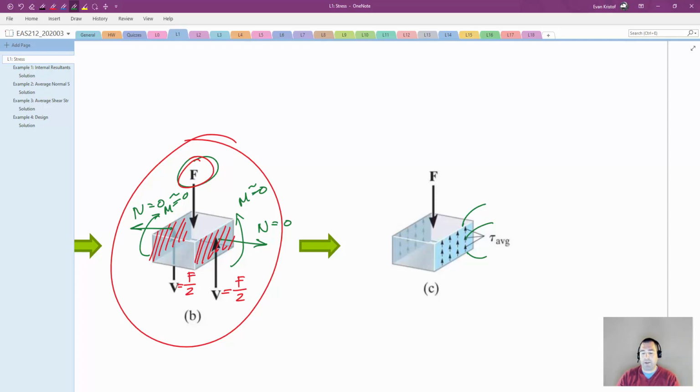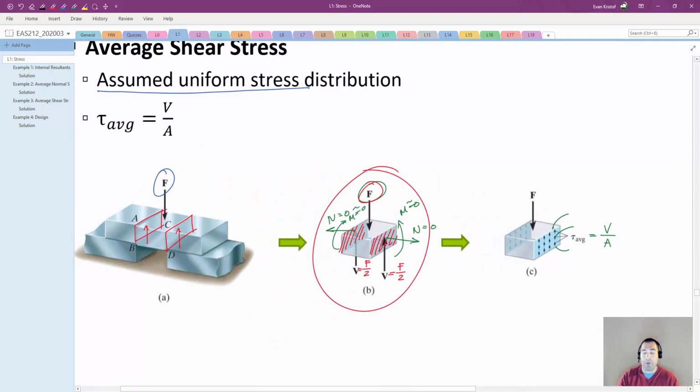For a rectangular section like this, I'll show you on another slide, the average shear stress that we calculate as V divided by A is actually about 50% lower than the maximum shear stress that the rectangular section will experience. But we still use average shear stress a lot in design calculations because we know what that difference is for specific shapes. This assumption helps us with the calculations right now, but in chapter 7 we're really going to sharpen the pencil and figure out that it's a pretty incorrect assumption.